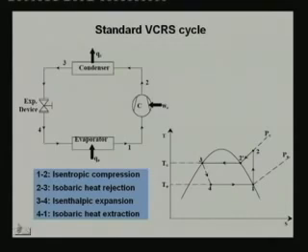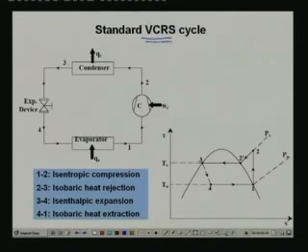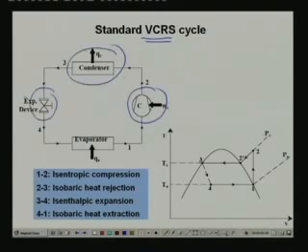You can see here that this cycle also, that means the standard Vapour compression cycle, consists of 4 basic components: the compressor, condenser, expansion device or a throttling device, and the evaporator. Okay. So, if you compare this cycle with the Carnot cycle, you will find that in terms of the components, the only difference is in the expansion device. There we were using a turbine, here we use a throttling valve. Okay. And the cycle on TS diagram is shown here.